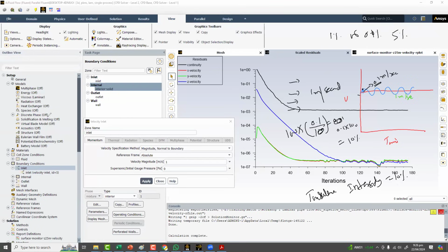When the flow is coming from the combustion chamber in a gas turbine engine and going to the high pressure turbine, turbulence intensity may be 20%. So it has to be the value that is particular for the particular situation. That value should be inputted to our simulation.